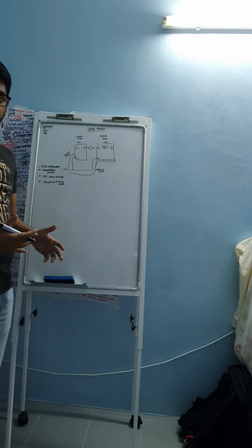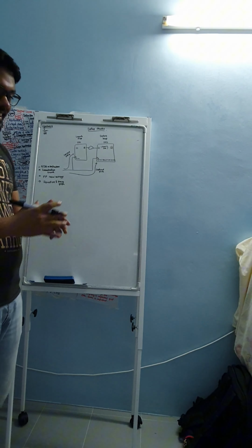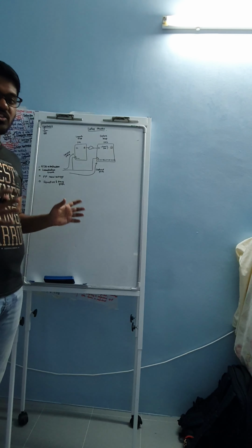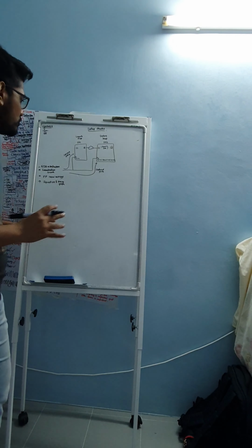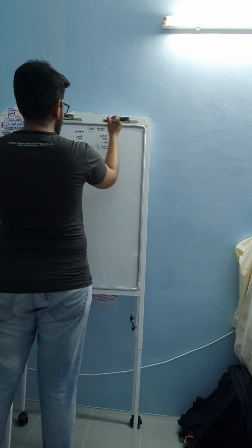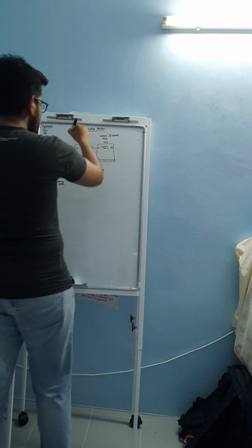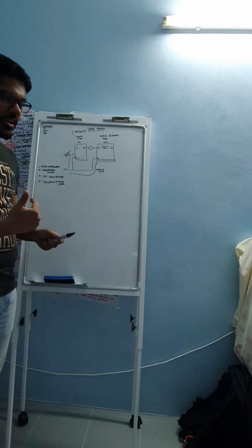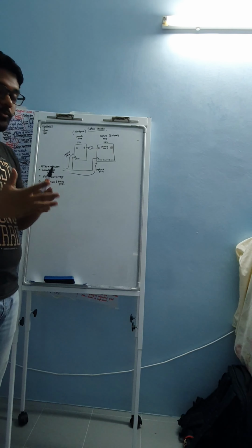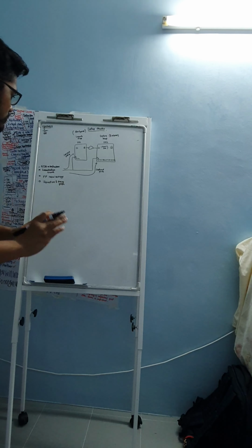On top of this, we will not see these pictures in your run or in your tools. This is like a cross-sectional view, but in a timing report you would see this as a start point, and this is your end point. You really need to understand this, because when you read your timing reports it will be another level or part of the analysis, but the methodology is always the same.